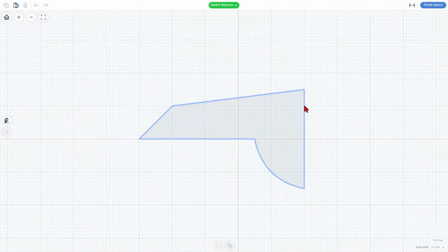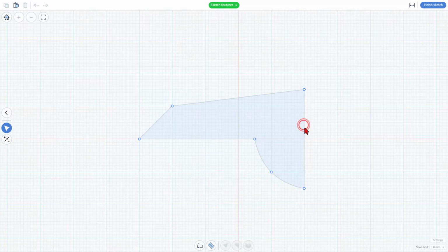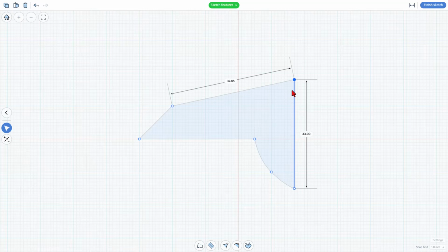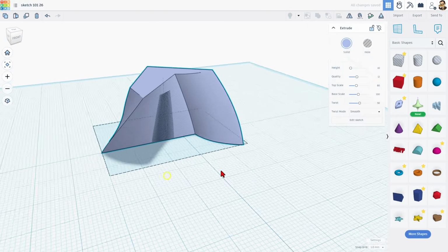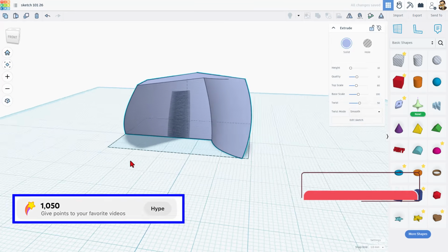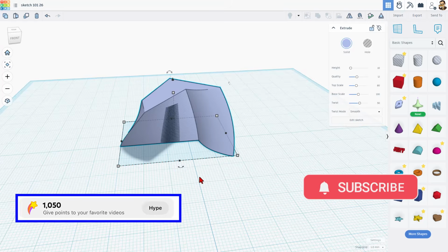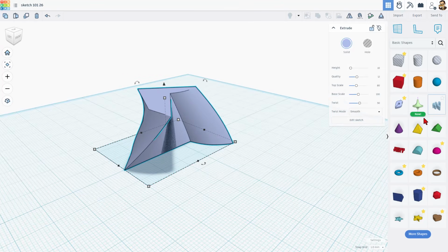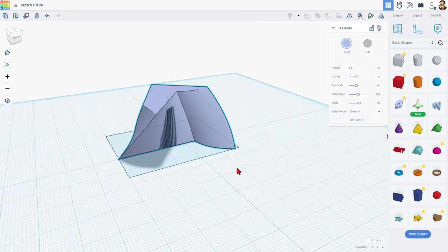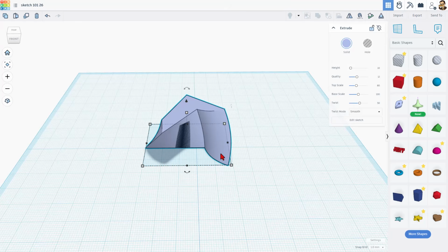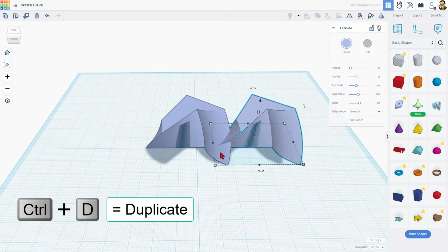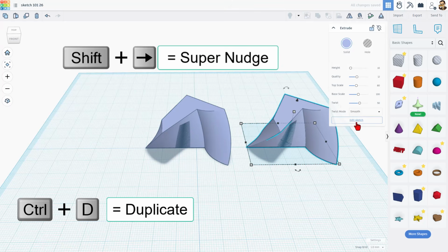And once again, you can look at this and say, oh my gosh, we took this design, easily drew it by using the smooth curves, adjusted it by dragging the points using the arrow keys to whatever you want, and when you hit Finish Sketch, bang, it twists, stretches, and revolves it to make something fantastic. Finding this part in these options is just not possible. Let's duplicate this. Control D is duplicate. I'm going to move it to the side, and let me show you something else.